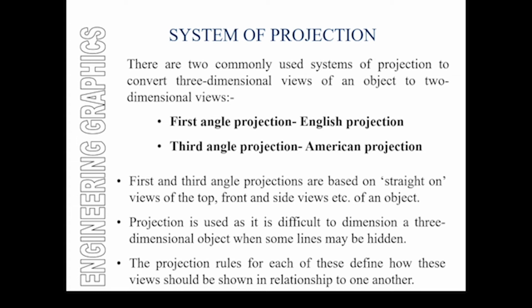That's why we tend to use 2D projections of a complicated 3D object. By the time you say, I'm not going to worry about all the dimensions, I'm just going to look at the 2 dimensions, and you look at the object from different possible views, you get a bunch of 2D views, which then allow you to put together all the information in 3D.